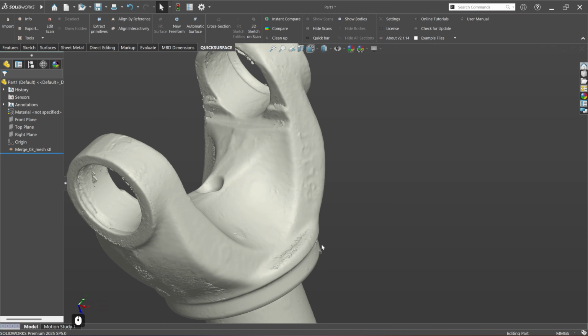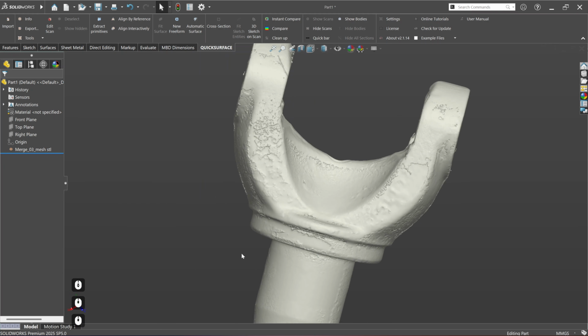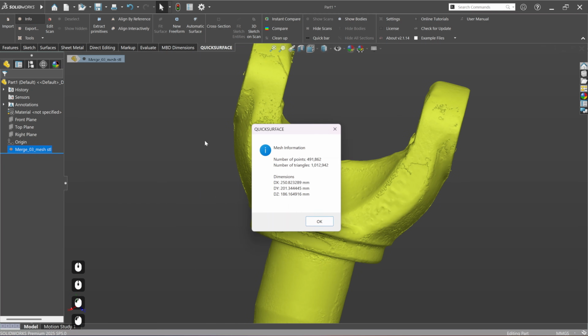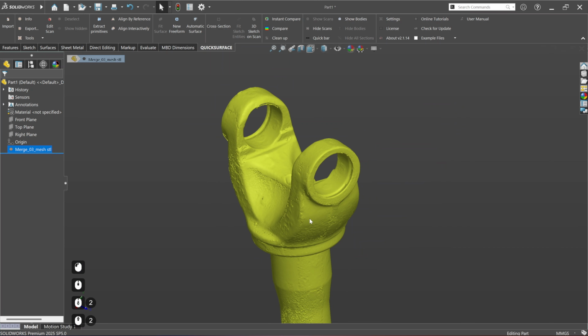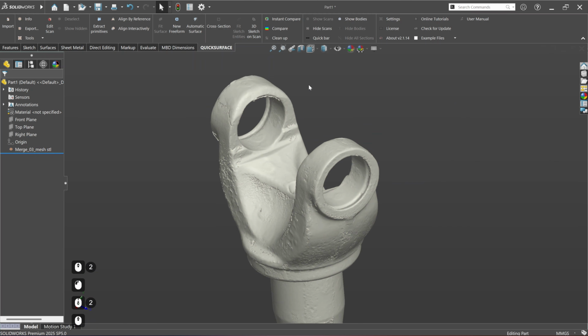So if you have such features, you can consider keeping the original mesh or part of the original mesh to later be able to reproduce these part numbers or super small features. Otherwise, this is the way to go, because currently you can see we have just 1 million instead of 10 millions of triangles, and this will save some sweat of your system hardware.